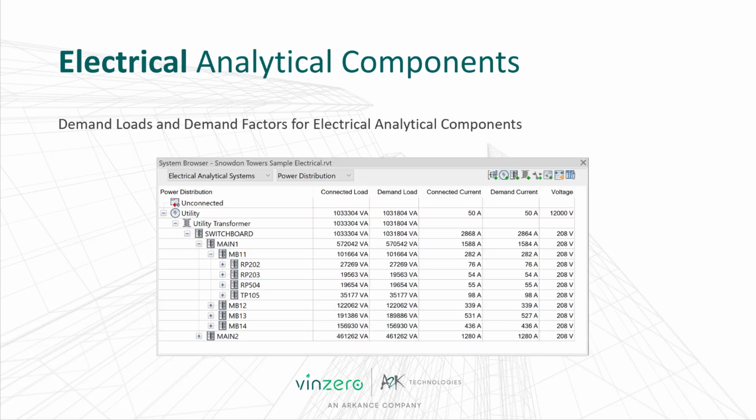Demand loads and demand factors for electrical analytical components. By specifying the classifications for each electrical equipment load and applying the demand factors, the currents and demand loads are calculated. The total connected and demand load are also schedulable. This gives enhanced visibility to electrical calculations.